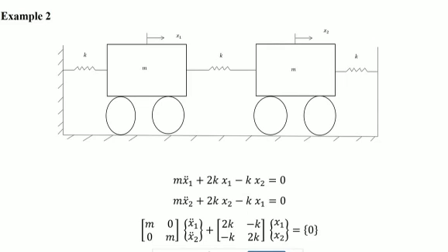That means u1 and u2, the shape defining terms or the proportional displacement defining terms, they are different, but the time function is same for both the cases. That means instead of the double derivative, you can substitute x1 double dot equal to u1 f double dot t, and then x2 double dot equal to u2 f double dot t, isn't it?